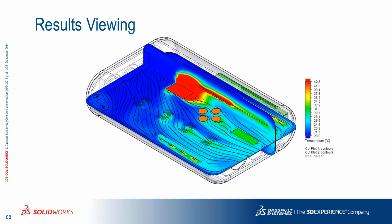Now, again, one of the nice things about flow simulation is you can go ahead and take section plots. You might be interested in analyzing a local area of the design where you want to slice that area and look at things like temperature, velocity, pressure, turbulence information. So you can slice and dice your results using this section plot in flow simulation.